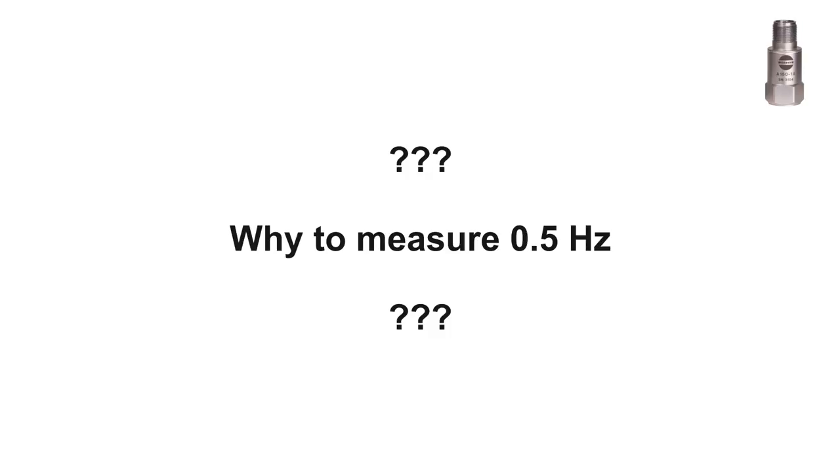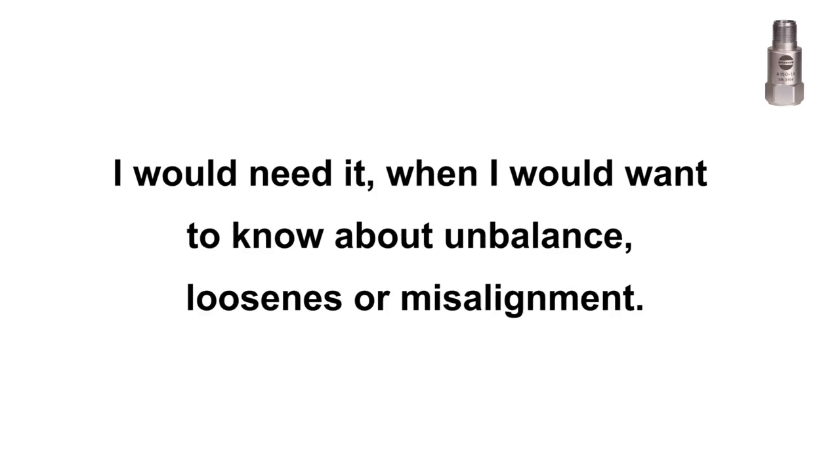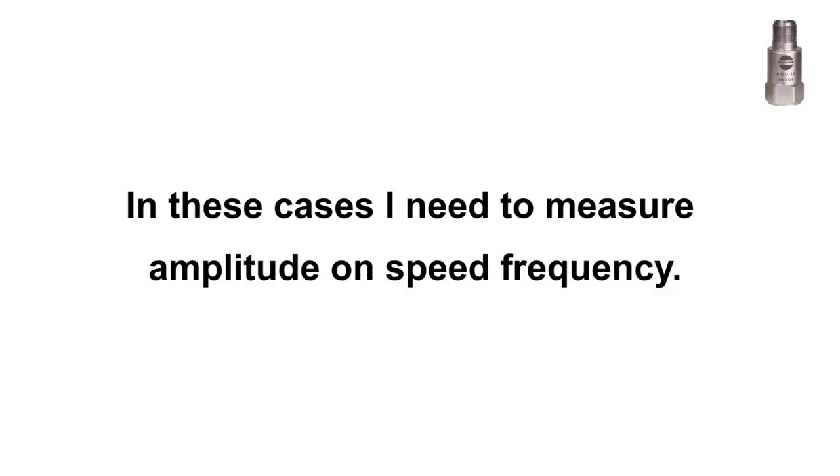But let's go back to the basic question. Why to measure the amplitude on half Hz? The answer is simple. I would need it when I would want to balance the machine or investigate the looseness or misalignment. In these cases, I need to measure the level on speed frequency. But I do not know who wants to do it.